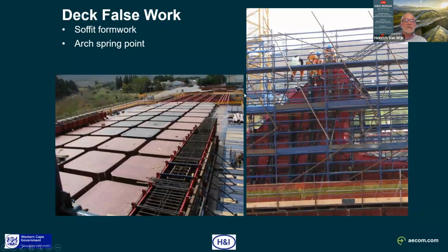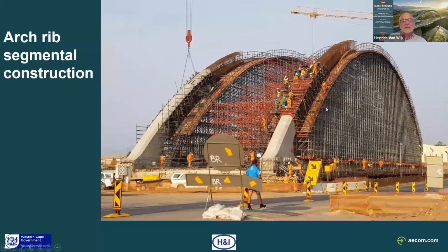Soffit formwork and the arch spring point. You can see the coffer system that was provided to construct and cast the deck in stages. And just the last view of the arch rib as it was constructed in segments over a period of time on false work.